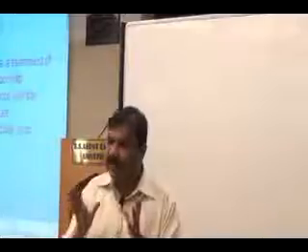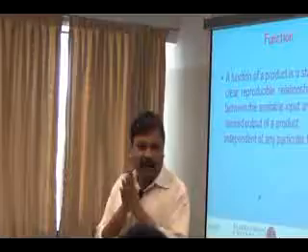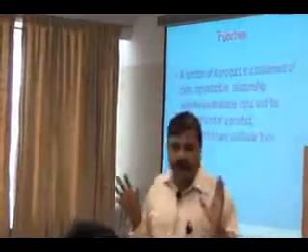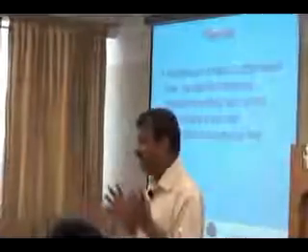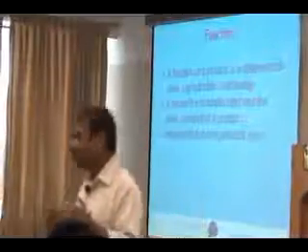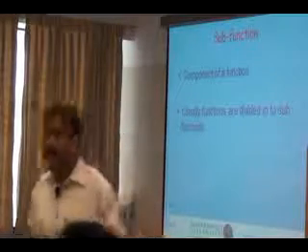It should be generic and it should provide scope for innovation also. Now having decided the overall function, it should use only the muscular energy from human beings as inputs, and it should help me in commuting from one place to another. Having decided this, what are all the sub-functions that are to be performed if I want to achieve this particular function?